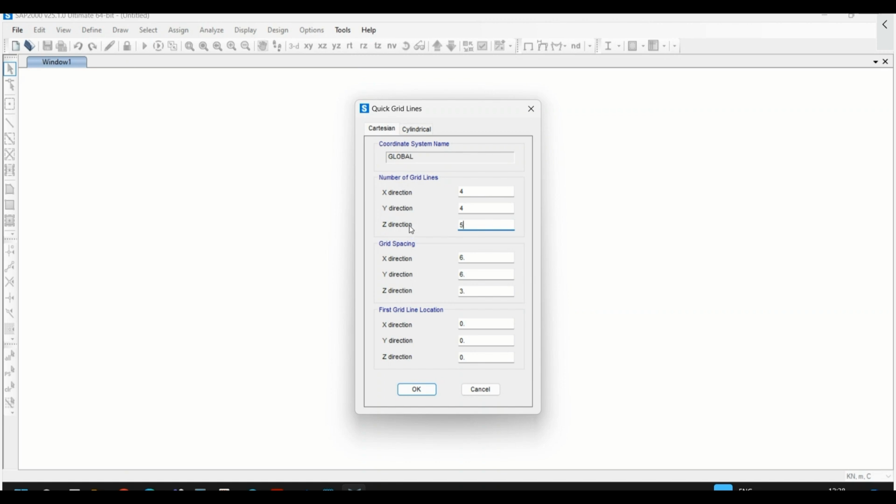and then there is a local coordinate system for the members, starting from a joint, line, area. Those are labeled as 1, 2, 3. Both will follow the right hand rule. You open the first three fingers of your right hand. Thumb is X, index is Y, middle finger is Z. So by default Z is along the height of the building. So when you look at the structure in a plan view, you'll get to see X and Y, and Z will be along the height of the structure.